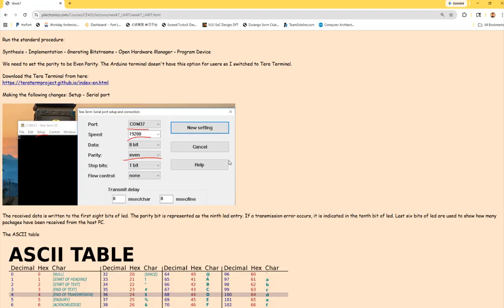When you use the Arduino, you plug it in and open up the serial monitor, it's able to read. Remember Serial.print, println, these kinds of commands? That is actually a TX command from your microcontroller. Even though it's called a print, it's actually sending from the microcontroller to the serial monitor, so it's basically using the TX port.